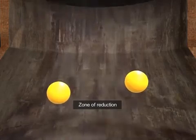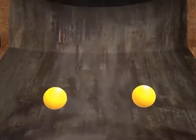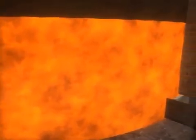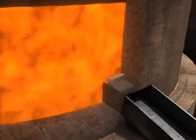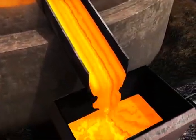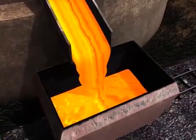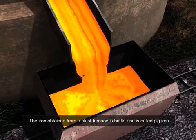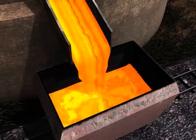As the iron descends down through the hotter regions of the furnace, it melts. Lower down the furnace, where the temperature is high, any unreduced ore is reduced directly by carbon. The molten iron collects at the bottom of the furnace and is tapped periodically. It is poured into sand molds and allowed to cool and solidify. The iron obtained from a blast furnace is brittle and is called pig iron.